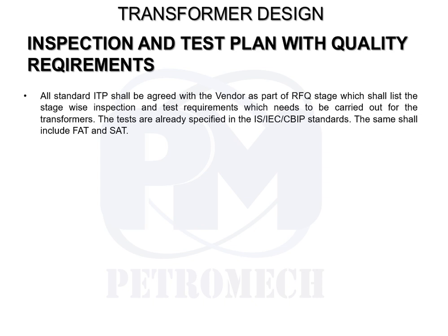Now, during this testing and inspection, I would like to emphasize one important point. Please take note of it. It's very important that while many of the class 1 vendors in India do have a NABL certified test bench, which says that they can do these type tests in their own NABL certified lab in their manufacturing facility, there may be a chance of speculation with some data in their own testing lab.